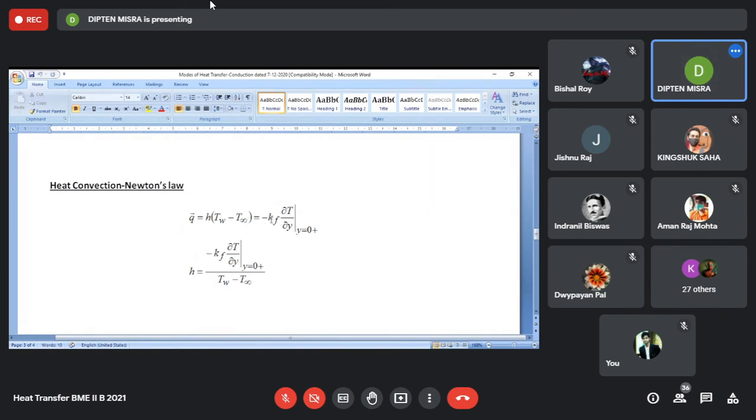Because this particle is sticking on the wall due to the no-slip phenomenon, because of viscosity, there also it is by conduction. We can apply the law of heat conduction as minus k suffix f. We highlight this f to indicate that this conductivity pertains to the fluid. The conductivity of the fluid multiplied by the temperature gradient along y, evaluated at y equal to 0 plus, or y equal to 0.